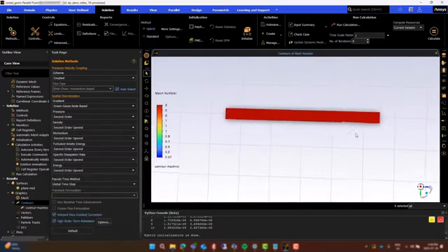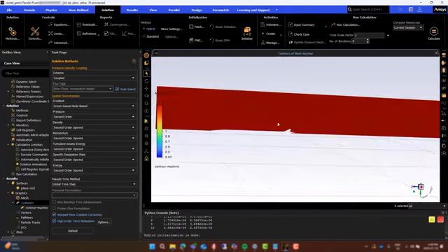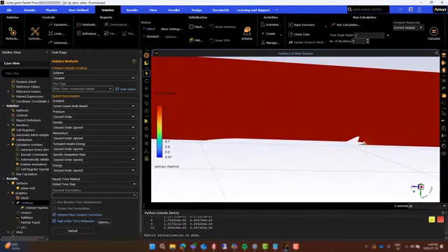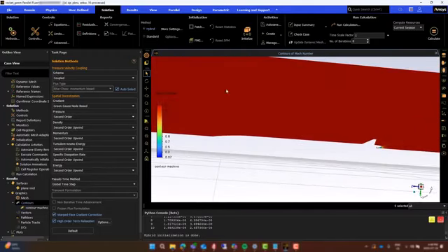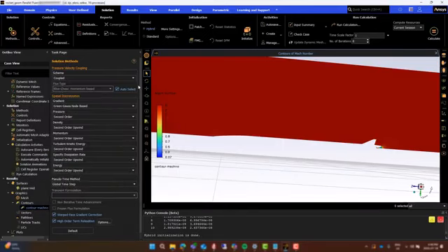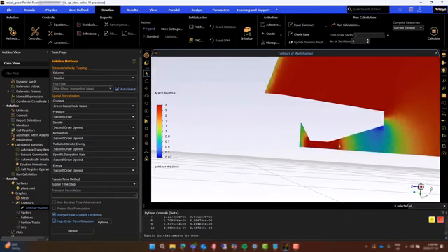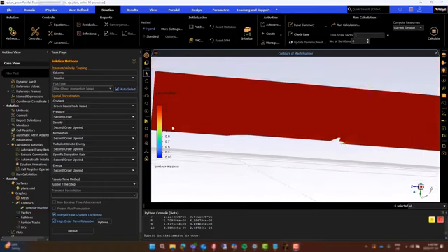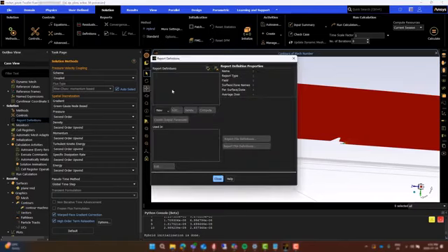We can also readjust and set the default view in this post-processing object to align with our coordinate system. By inspecting the Mach number contours, we can see how the hybrid initialization method interpolates the starting domain values between various boundary conditions.